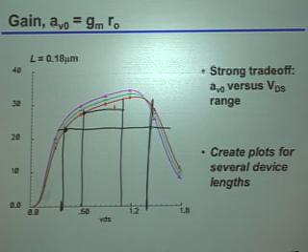So which of the two do you think you might want to choose, for each of those two vectors? Let's maybe do channel length first. Which channel length would you want to choose? Yeah, the smallest channel length you can get, right? Because once you know you can meet the gain, why would you go any longer on channel length? Longer channel length only gives you more parasitics, makes the devices larger, everything just gets worse.